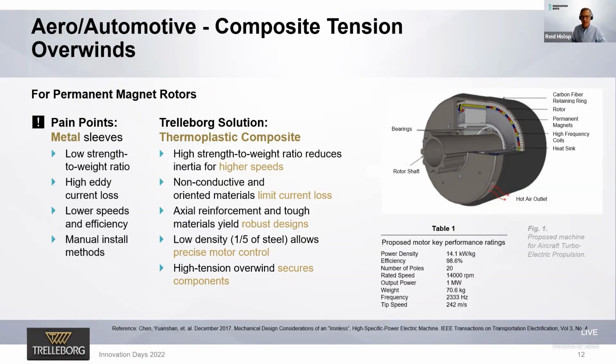What ends up happening is we place and consolidate the thermoplastic materials directly onto the magnet rotor assembly. These composites act as a retaining sleeve to hold the magnets in place when they're spun at high RPMs. The incumbent materials that we see today are metallic or thermoset, and they are manufactured as sleeves that must be press fit onto the rotor assembly. Well, many of you know that carbon fiber and glass fibers really don't like to be stretched. So the press fitting option is difficult, challenging, and can be time consuming. It ends up adding some uncertainty to the assembly process.